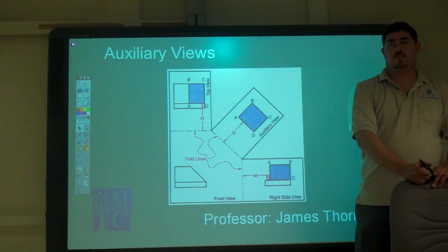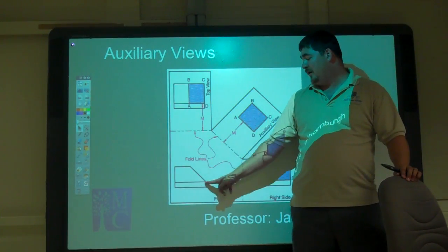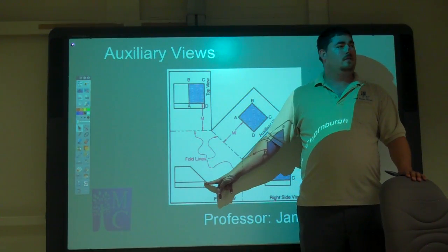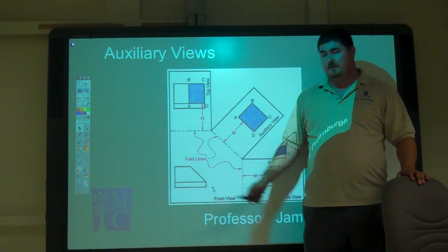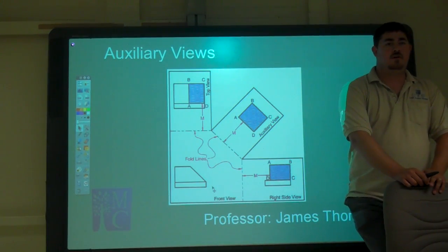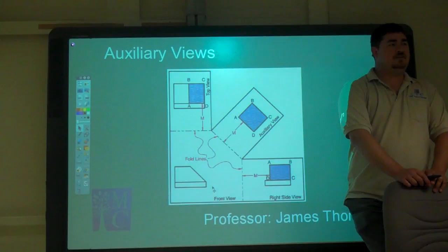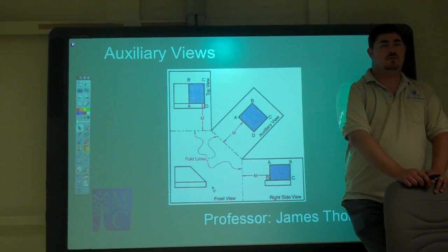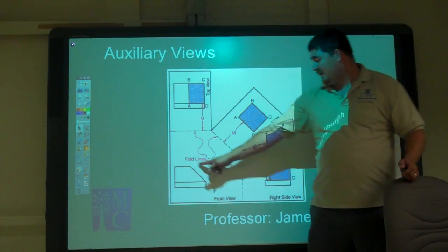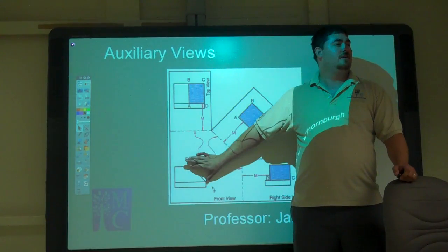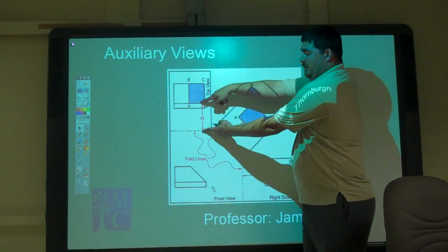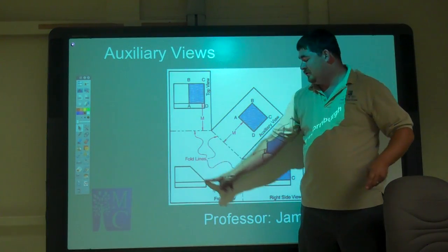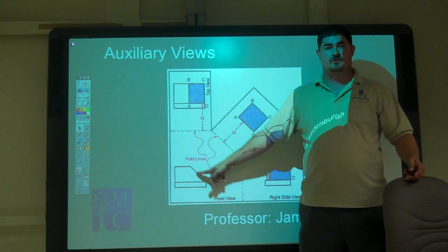Okay? And so the edge view was what? What was that line? This inclined line? What is that line? Can I measure that line and tell how long that line is? Yes, right? This line right here, I can measure and tell how long that is. Because here I came parallel to the line, the folding plane and the line are parallel here. So it means here it's true length. So this is true length.